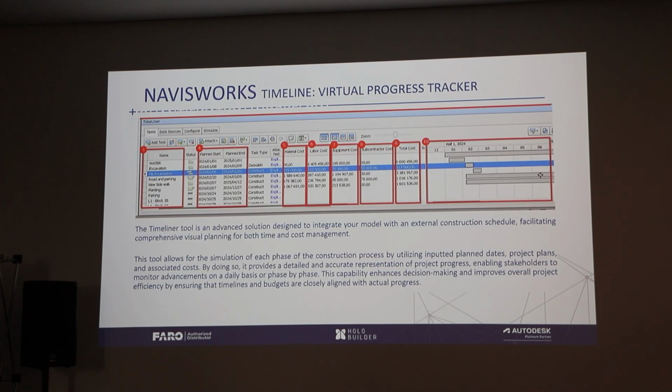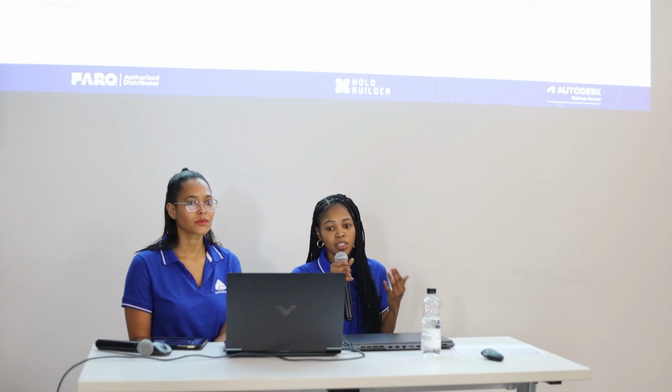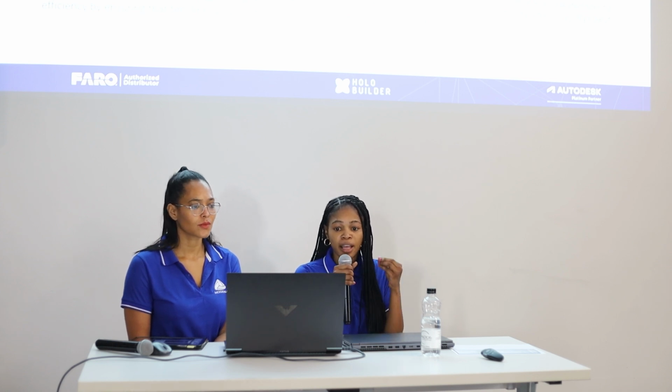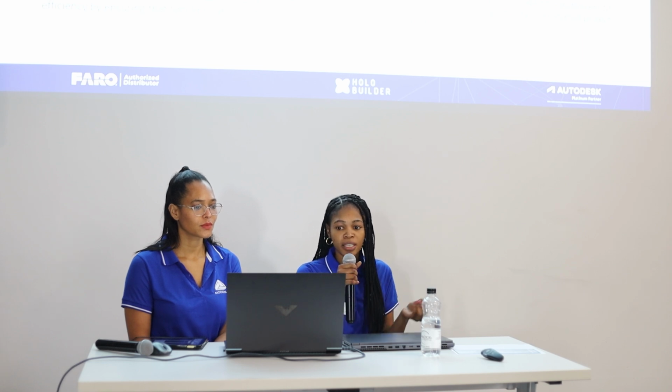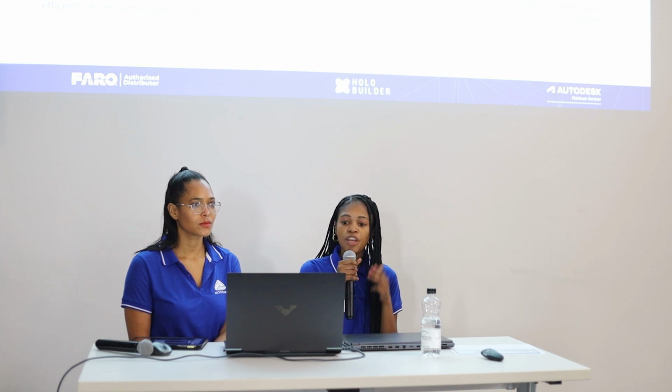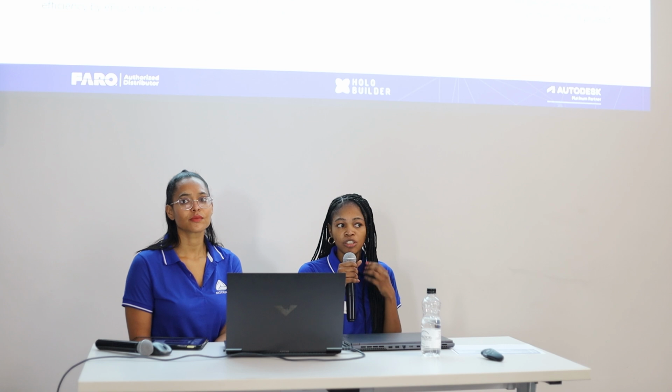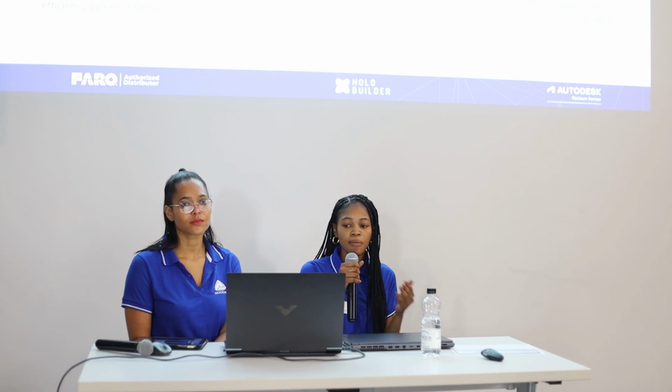And then now, looking back again at the timeline, once you've done the quantification in Navisworks from the start, you can input when you plan on starting certain processes. For instance, the excavation, you can input when you plan to end it, and you can input the material cost, the equipment cost, the subcontractor cost, the total cost. You can also input the machinery as well, when it needs to be serviced after how many weeks.